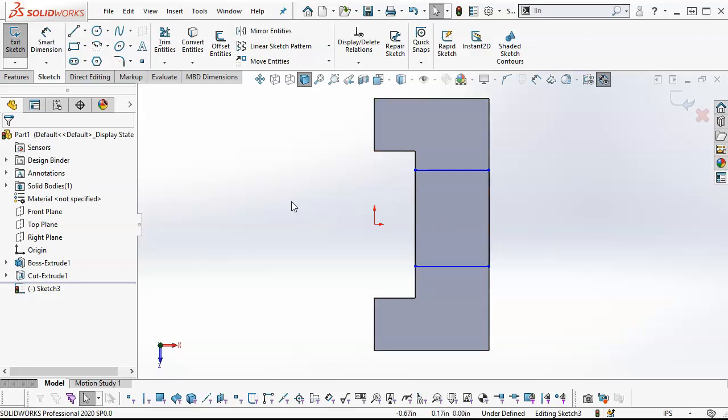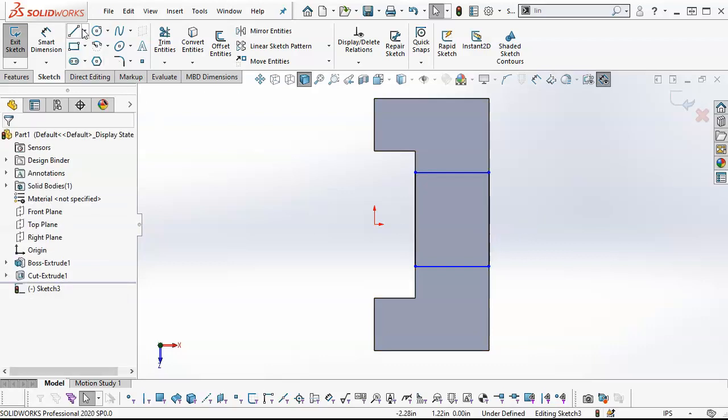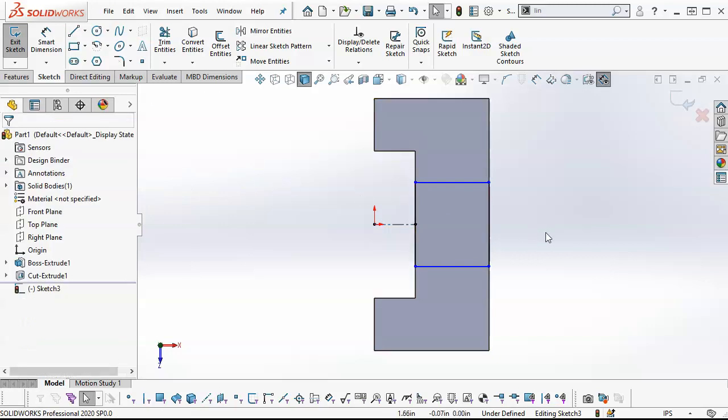sketch, the rectangle command. And then we need to orient this to the part, or to the origin. I could apply dimensions, and then I could also go into the line and apply a center line. So if I go to the center, notice that that isn't quite horizontal, but I have a horizontal relation available. That will pull it into place. And I'm going back to the select.